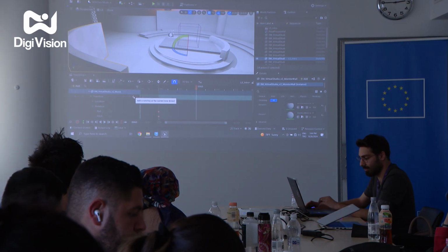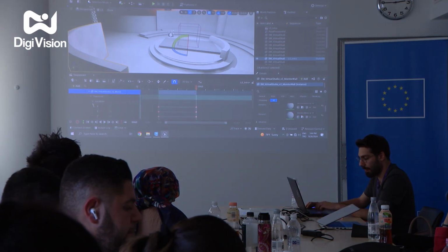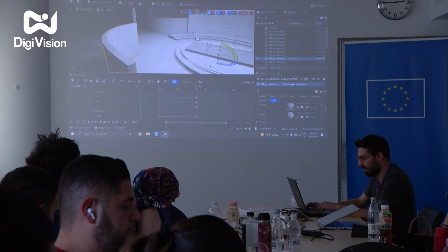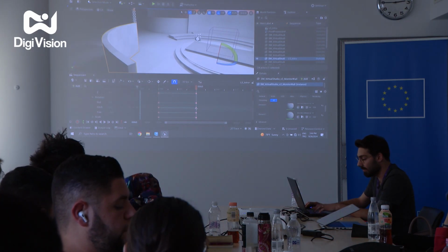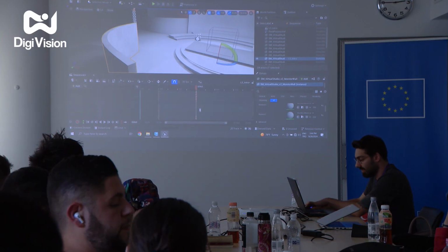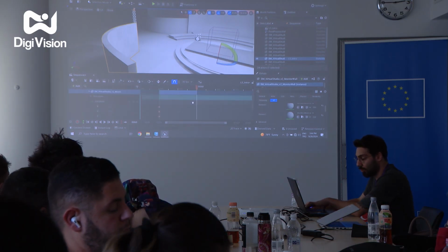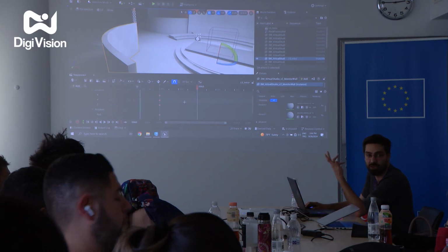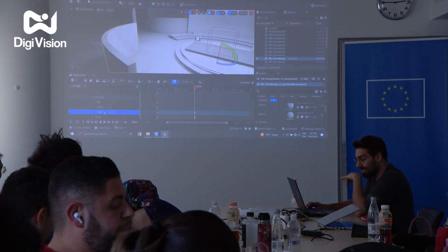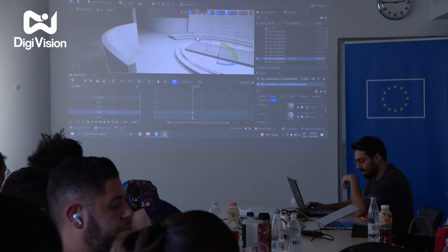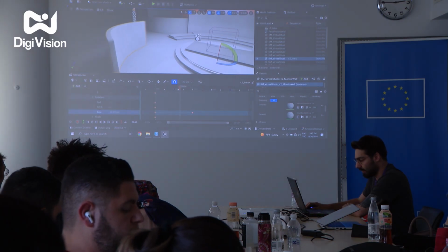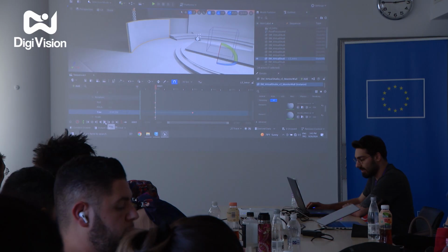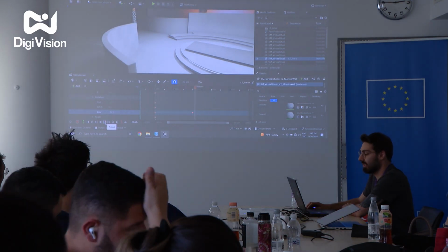We only selected a single axis on the rotation. So as you can see, we can remove the other tracks because we didn't make any changes to the location. We only modified the rotation. Having only this rotation info will be enough for us. So we can remove these tracks and directly manipulate this rotation axis. And as you can see, when I played it, it directly moves.